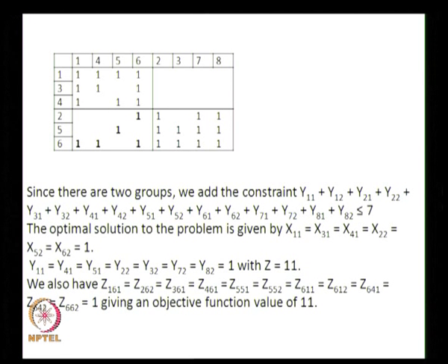If we duplicate machine number 5, there will be 1 intercell move, and we duplicate machine number 2, there will be 0 intercell moves. So, the actual solution with 0 intercell moves is when group 1 has 1, 2, 3, 4, 5, 6 and group 2 has 2, 5, 6.